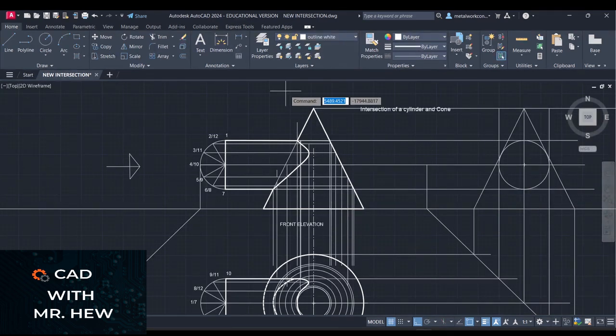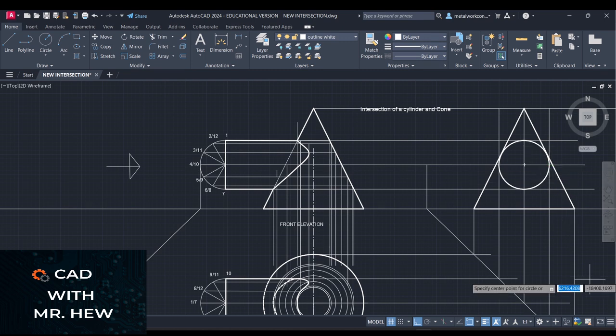What we're gonna do now, we're gonna darken it, all right? So you're gonna take, if you're using a pencil, a 4H pencil. I'm gonna come like this, there, there, there, there, enter, right? Then we're gonna draw the circle, center, radius there, enter. So this will be the completed end elevation, all right?